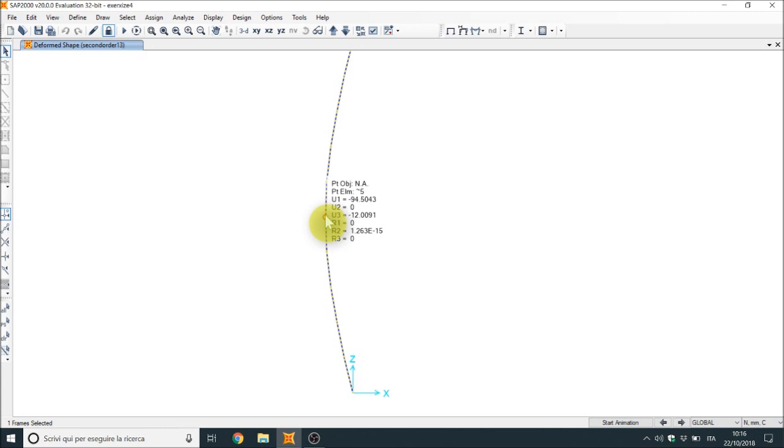And then the software finds the equilibrium but in a different position. Sometimes if you run a multi-step automatic analysis, maybe you will see only this 94 value. And you will see, okay, 94 is a good displacement for me. And you are not considering that this is not the forced equilibrium position. Because in the forced equilibrium position you have a displacement that is quite infinite.